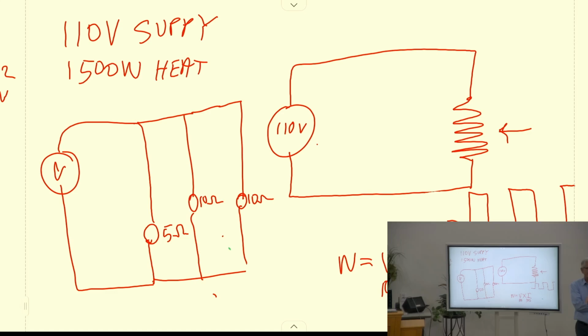It's much more complicated. Like in your car, when you buy an inverter, where you plug it into your cigarette lighter and you get 120 out, that's DC to AC. And that's much more complicated than the other direction, because in the other direction you can use rectifiers, which are diodes.